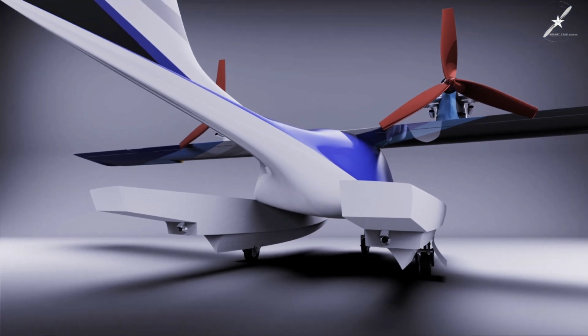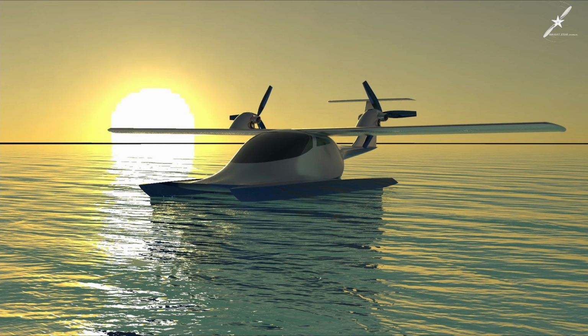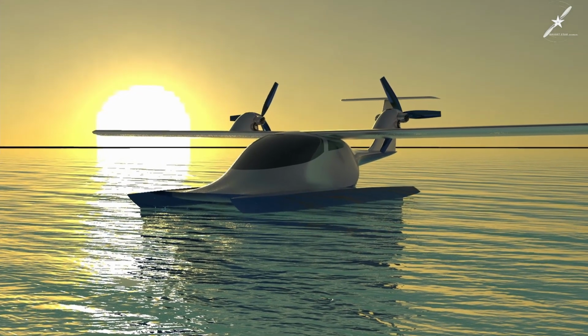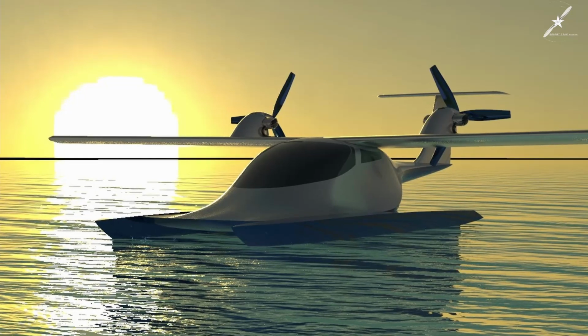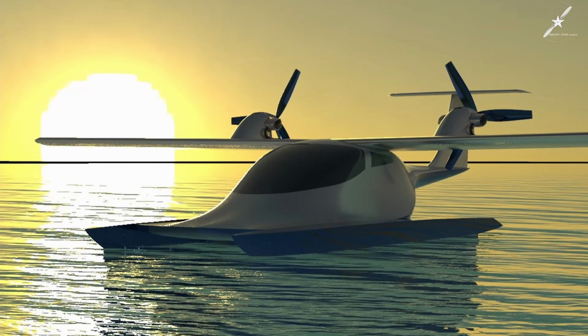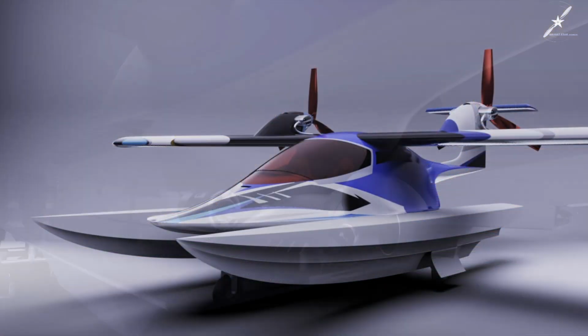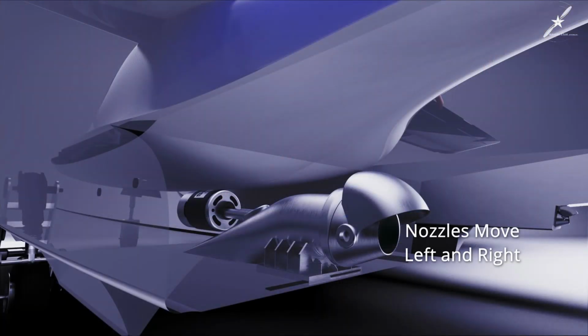They will be controlled by a joystick located in the center console. This will allow the pilot to shut down the engines as they approach a dock or beach with people standing around and not endanger them with the propeller still spinning. The jet thrusters are like trolling motors to gently approach the dock or beach. These thrusters also have thrust vectoring and reverse, which is used for slowing down.